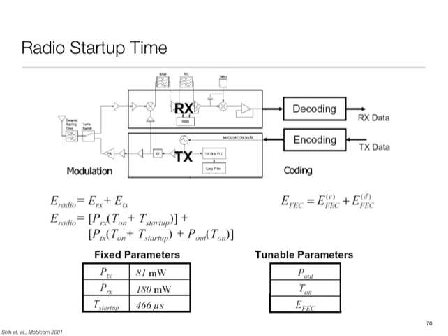So can you think of situations where the energy I spent to send a packet is wasted? The receiver is not ready to receive. Okay, receiver is not ready. What else? It's not able to successfully decode the message. Okay, message is too noisy. Okay, what else? My protocol was stupid enough to schedule more than one transmitter at the same time, for example, right? I mean, then I collide. So that would be another example.